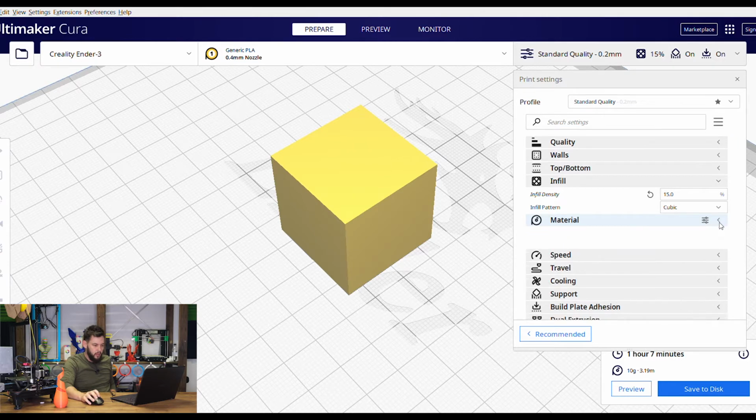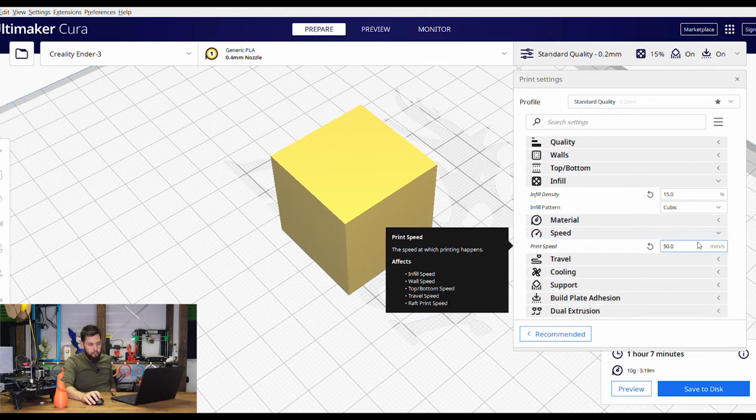That's really important. So your speed, by default, most Creality machines or most Cartesian-based machines will be at around 50, 55, and 60 millimeters per second by stock. You can tune it to be a little bit faster depending on what firmware is on there. For example, the Delta machines, I've seen guys print some insane things at insane speed. So I think I saw a machine that did 150 millimeters per second. Like it's actually scary to watch.